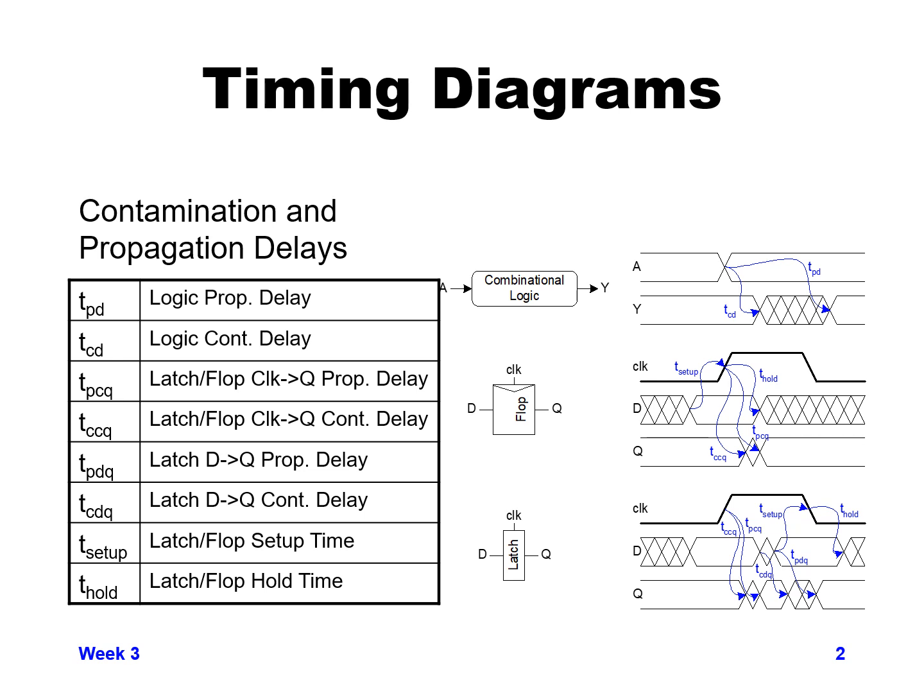One is you get an output Q that's a propagation delay. That's the longest amount of time that it takes for Q to change based on clock rising. And one is a contamination delay, which is the shortest amount of time, the quickest that a value can come through, based on the clock edge rising.